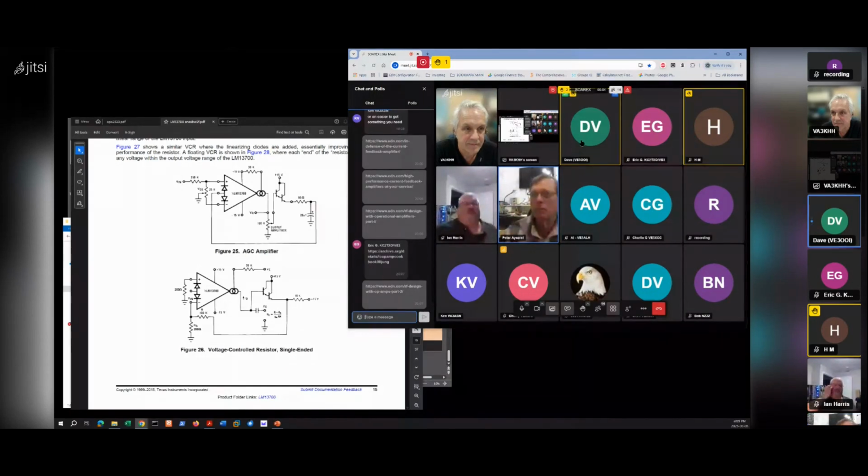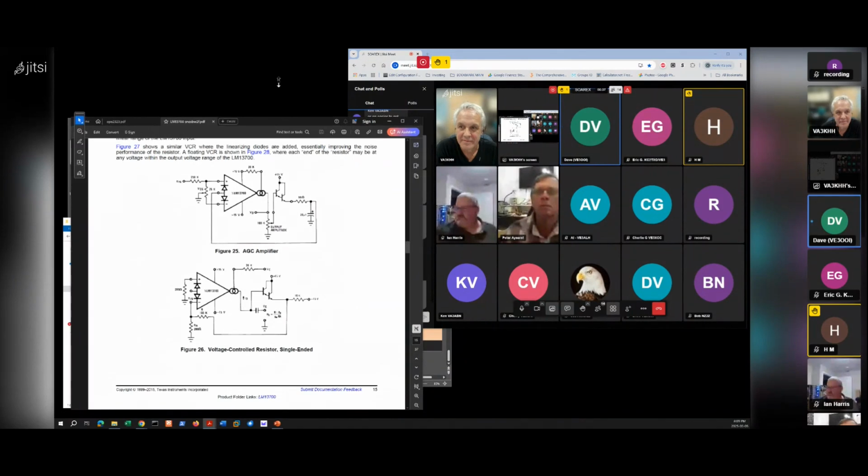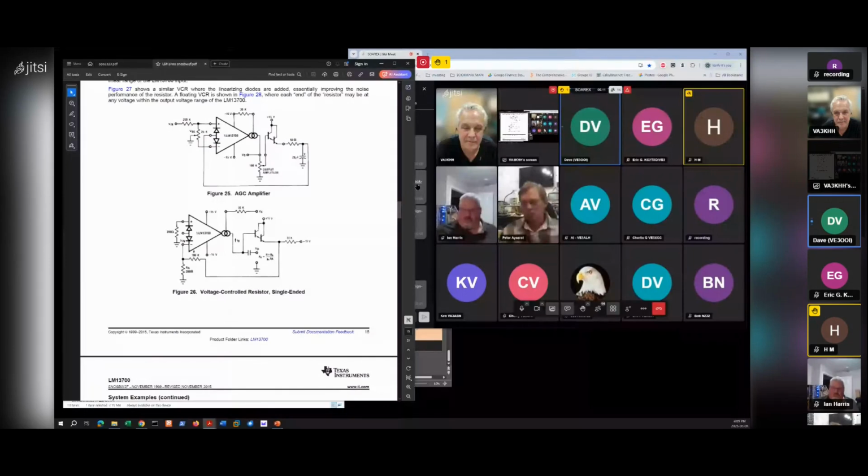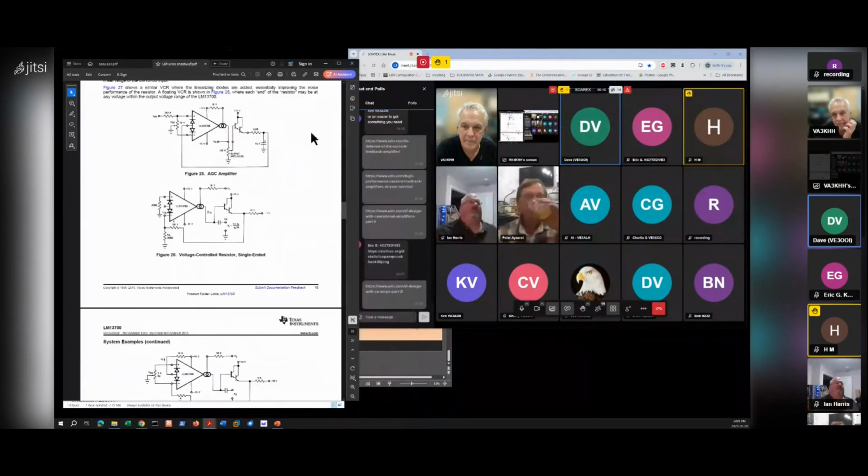Yeah, got to find my mute button. Kevin, one of the things with those voltage and current feedback amps, I've had problems with bandwidth rolling off, and not just the gain bandwidth product. With the current feedback amps, I've never had them perform the way that they say.